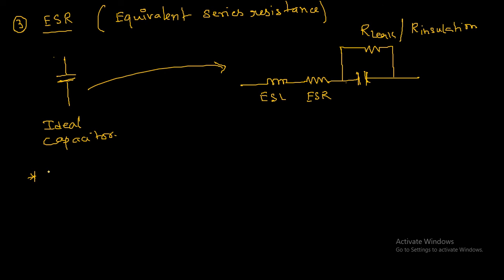So it becomes apparent that a high quality dielectric increases the possible capacitance. The actual storage capacity of the capacitor also improves as the self discharge drops with increasing resistance. So if you keep increasing this leakage resistance or insulation resistance, it goes higher and higher, and self discharge decreases.